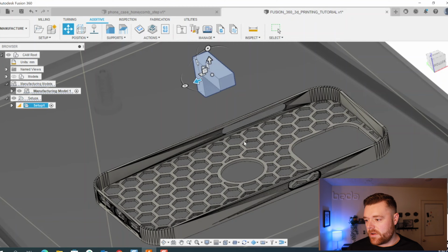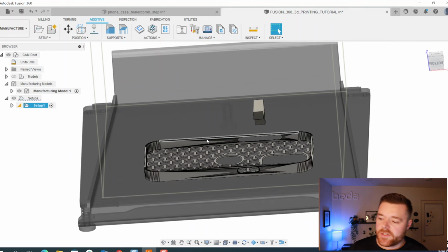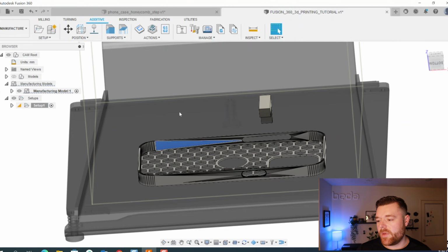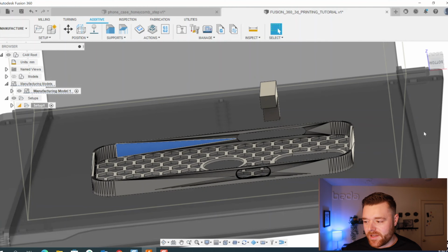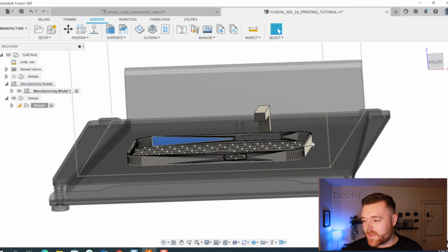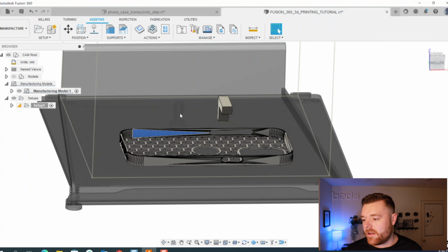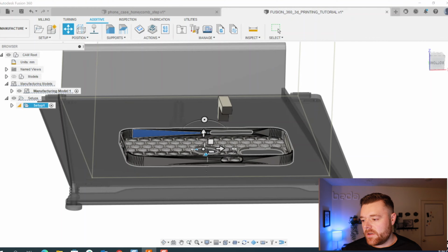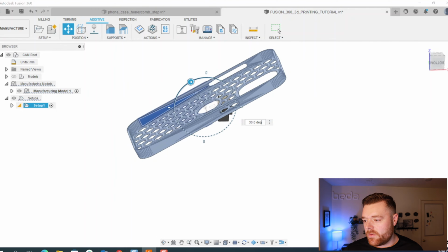Enter. Okay, everything looks good to go. Now, one thing I did want to mention is if you do bring in a part, maybe some organic geometry, because not every print is going to be as perfect as this with a flat base, an iPhone as reference, and just a block model. So what I did the other day is, if we go to move components, let's bring this off the printer bed a little bit, and let's say we rotate it and hit enter.